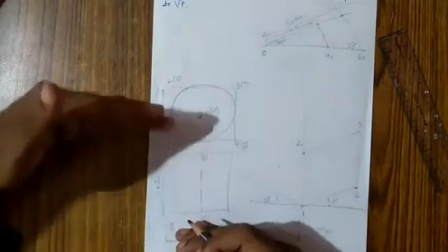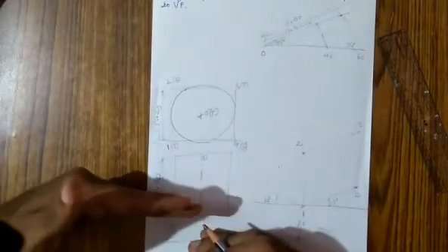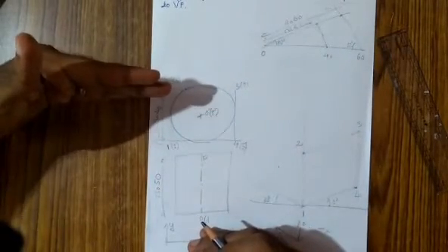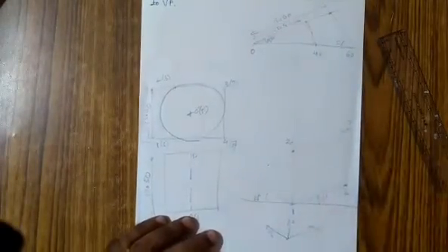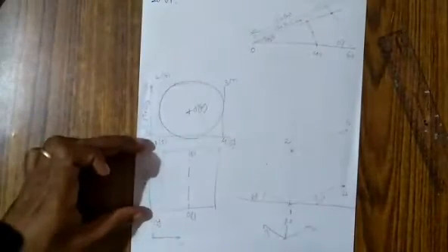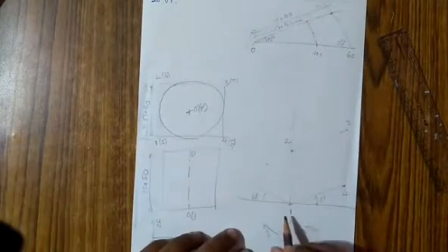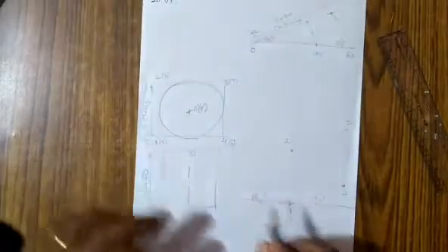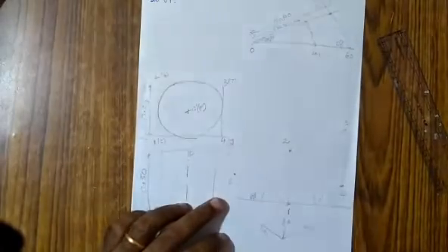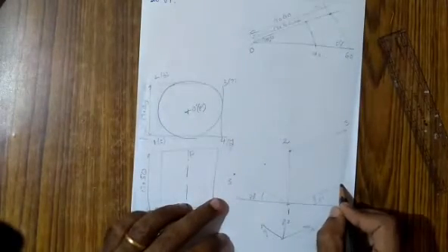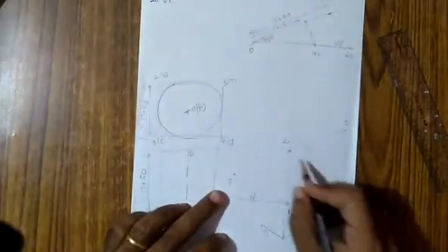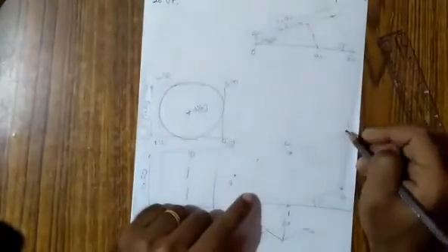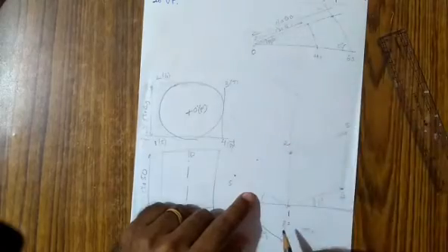Now it is extending backwards from this face 1, 2, 3, 4 to the back square face, which is 5, 6, 7, 8. So what is the length? It's going to be ISO 50. So you can take this length in the y direction. So this is your point 5. Next through 4, you draw a line. Next through 5, you draw a line. Through 2, you draw a line parallel to the y direction, and next through 3 you draw a line parallel.